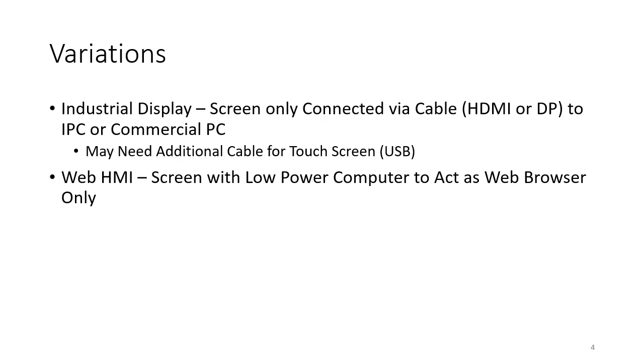Web HMI is a low-powered computer device, typically using a very simple CPU, and that just runs a web browser. So the idea of a web HMI, this is often combined with a central server, and then you could run that web HMI as like a kiosk type device, or possibly you could be using some sort of web-based graphics, possibly extending to a thin client, maybe using RDP or so on. But normally these web HMIs are very low powered computers. That brings the price down, but it also brings the performance down considerably as well. But in this case, typically the web HMI is a web browser only, and it would have to connect to some sort of server device.